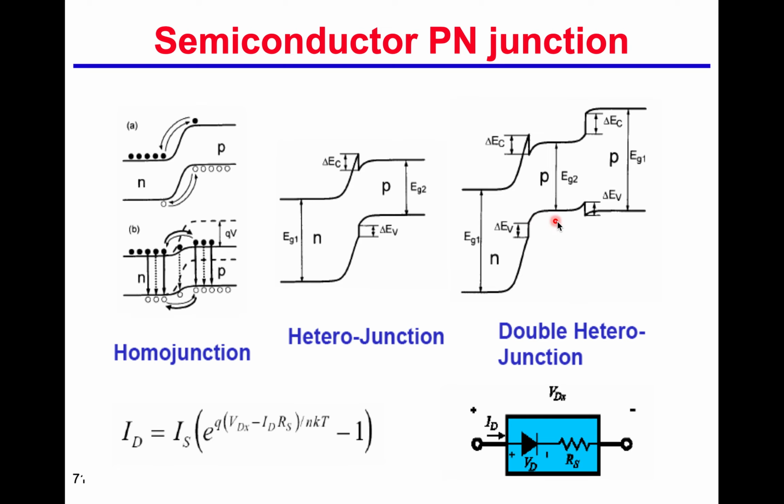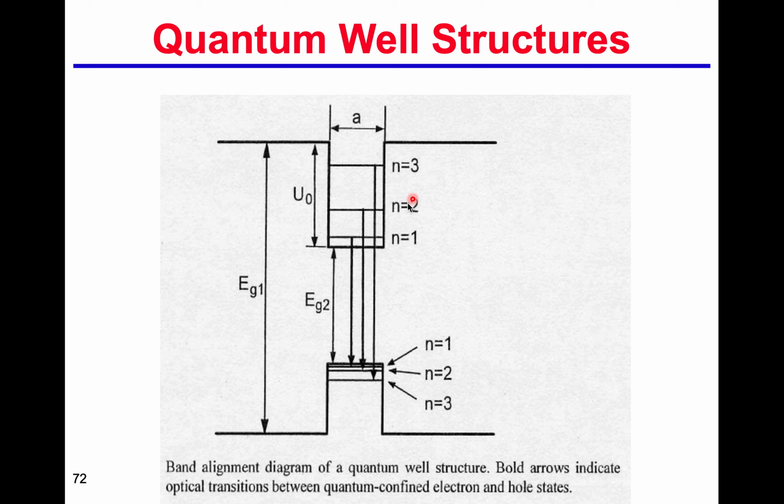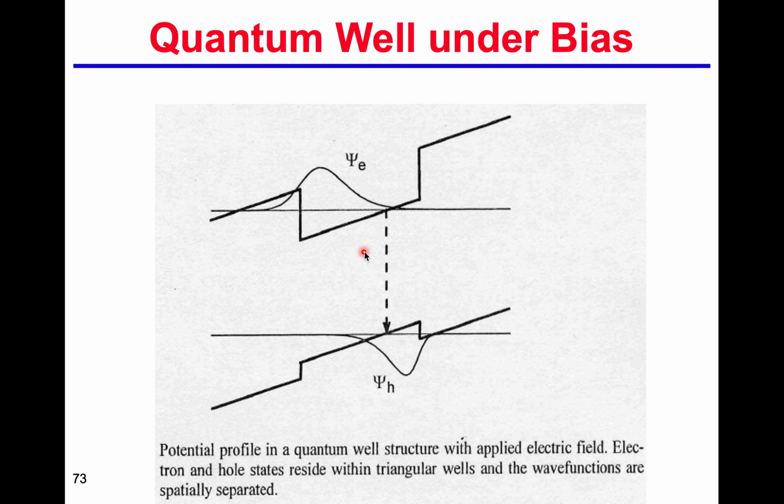So for the heterojunction material here, the feature size is about 1 micron. But if we can have a smaller feature, for example less than 100 nanometers, then we can quantize the energy, so we can tune the emission wavelengths, and that is very efficient. That provides us another possibility to tune the emission wavelengths, and it can also change the density of states, but I will not talk about that too much.